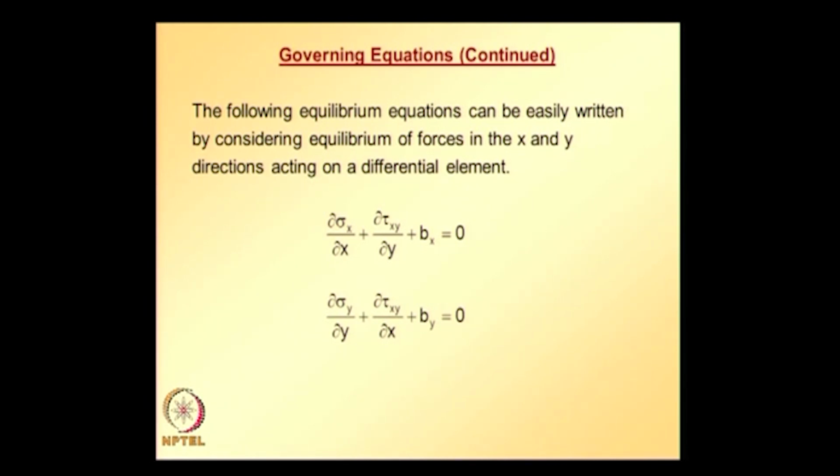So, now what we need to do is we need to express these equations in terms of displacements, because displacements are our primary variables which we need to solve. So, these equations can be expressed in terms of two displacement components, because we are looking at two dimensional elasticity problem.